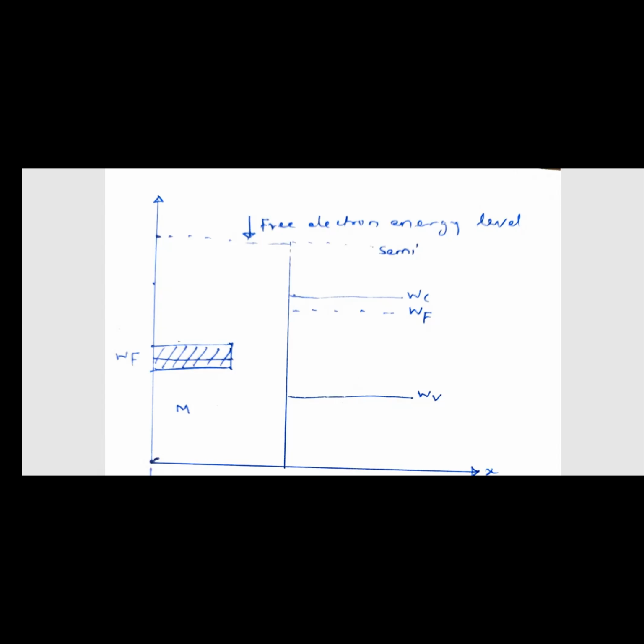Okay. So if this diode is forward biased, how to forward bias this diode? N type semiconductor material should be connected with the negative polarity of the biasing source, and the metal should be connected with the positive terminal of the source. So this condition is called forward bias. If the potential is sufficiently high to overcome the barrier potential, then there will be flow of electrons from semiconductor material to the metal.